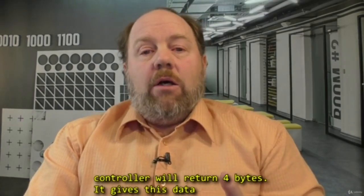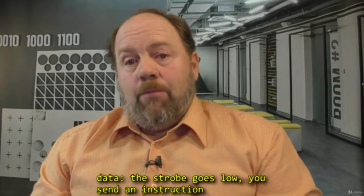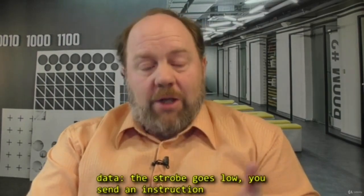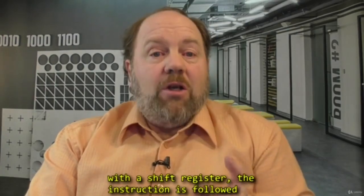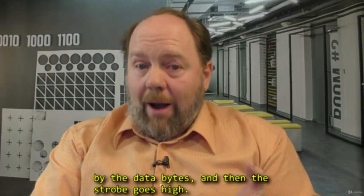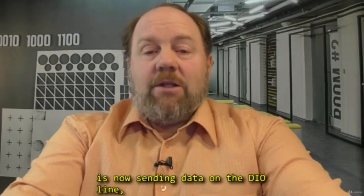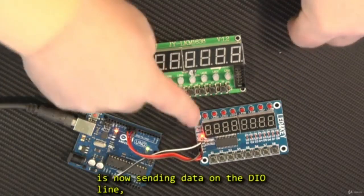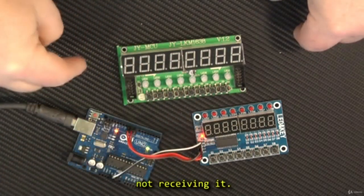It gives this data in a similar format to the other instructions and data. The strobe goes low. You send an instruction with a shift register. That instruction is followed by the data bytes, and then the strobe goes high. Now there's one significant difference. The controller is now sending data on the DIO line, not receiving it.